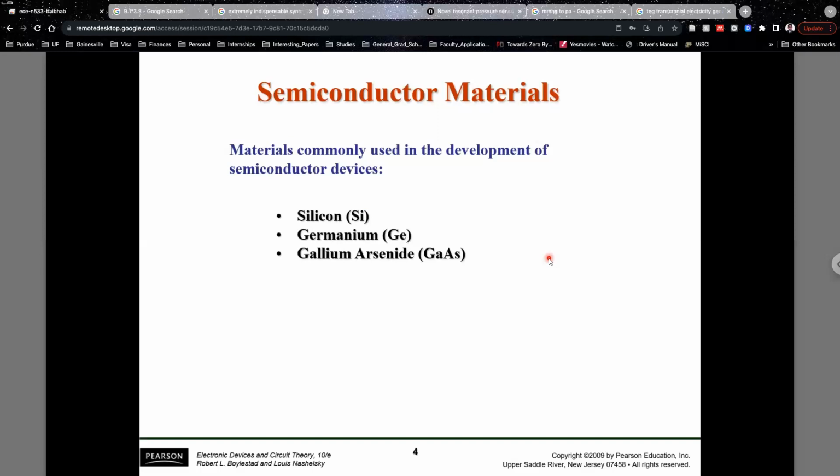But let's say you put a boron atom inside this structure. You put some impurities, let's say a boron atom. What will happen in this case, if you look into your periodic table, is that boron will have a valency of 3, just like silicon has a valency of 4. Silicon can be conjoined with 4 other atoms on 4 sides, whereas boron can only conjoin with 3 other atoms. So what would that mean? That it can be connected with this silicon here, this silicon over here, maybe another silicon over here. But there is a silicon on this side with which it cannot create a bond.